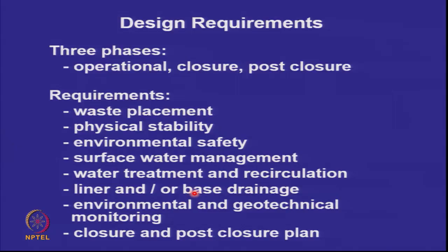Do you need a liner at the base of your pond? And if so, is it the same liner as you use for landfills? What monitoring do we have to do for the years of operation and closure and post-closure period? And finally, what is the plan? What is your long-term vision as to when you abandon the ash pond, would you have returned it to its original condition, or how would you have merged it into the ecosystem? So these are the design aspects which one has to consider.